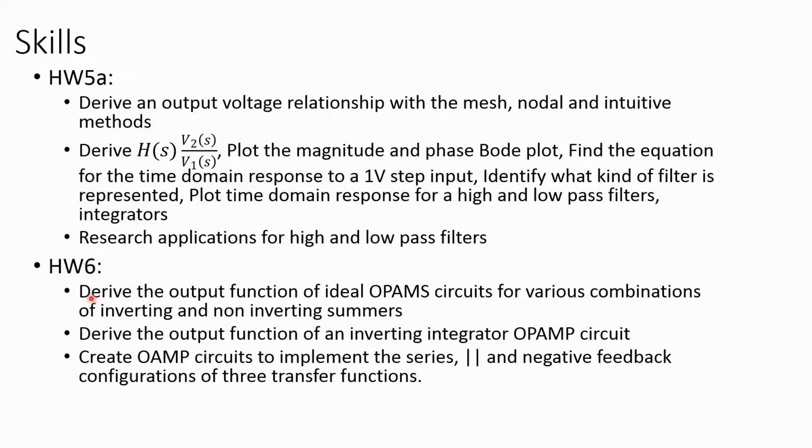Homework 6, derive the output function of ideal op-amp circuits for various combinations of inverting and non-inverting summers. This is really critical to the final project and the notch filter in EE110 lab. Derive the output functions of inverting integrator. You need to know this cold because the DF2 method relies on inverting integrators. And then create op-amp circuits.